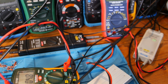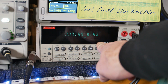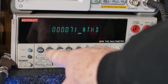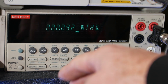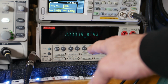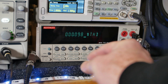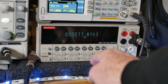Let's go look at the oscilloscope. Okay guys, and this is a Keithley THD meter. It's a 2015, a multimeter with the THD function. It's really awesome. I hit the shift key, hit THD, and it goes into this mode. It's jumping all over the place because it's automatically trying to find the frequency of the fundamental. After that, it uses a bandwidth filter to filter that frequency out and measures all the rest of the noise, the harmonics.